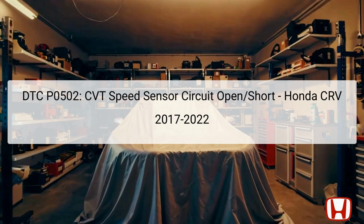Diagnostic Trouble Code, DTC P0502 indicates a specific issue related to the continuously variable transmission CVT speed sensor circuit. This error highlights an open or short circuit condition within the sensor's electrical system. The CVT speed sensor is crucial for monitoring the transmission's performance by providing real-time data that the Powertrain Control Module, PCM, uses to optimize shifting and engine performance.